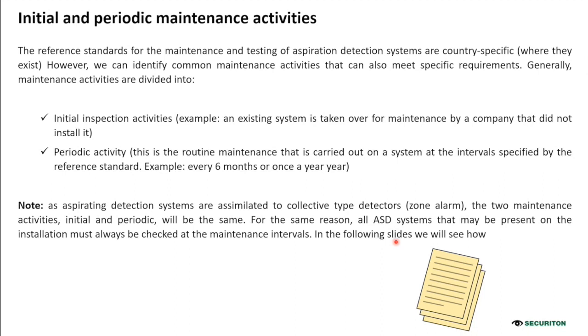For the same reason, because these detectors are assimilated to collective type detectors, if more than one ASD is present in the installation, they all have to be checked during the periodic maintenance.